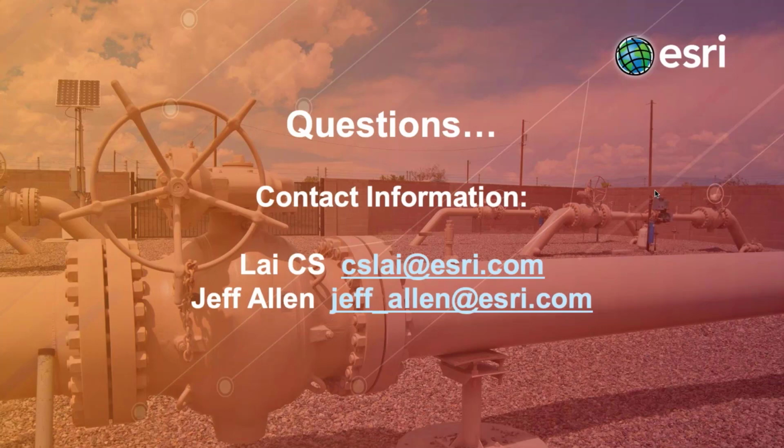Yeah, that's really interesting. So when we think about the pipe itself, we think about a couple of different things that are actually all interacting together. You have the larger pipe segments, where we have similar characteristics like OD, wall thickness, grade, manufacturer. We typically put those in as pipe segments. Then we have what we call the pipe lengths, which are the individual 40-foot joints that make up those larger pieces. And then between those joints, we have the welds.